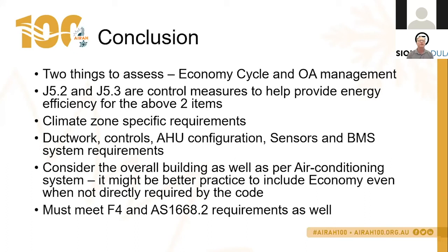Typically, you can't use kitchen exhaust air in a heat recovery situation. In regards to economy cycle, yes, you would definitely use economy cycle for the makeup air path for a kitchen exhaust, because you're increasing your outdoor air rate to balance your kitchen exhaust requirement anyway.